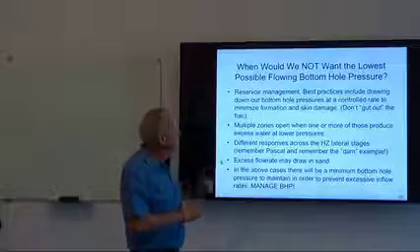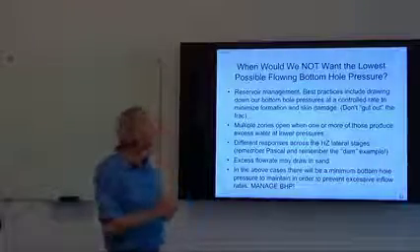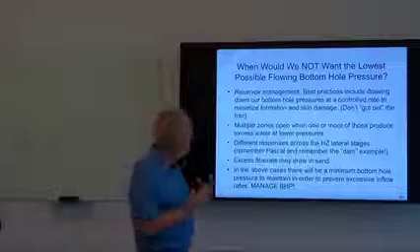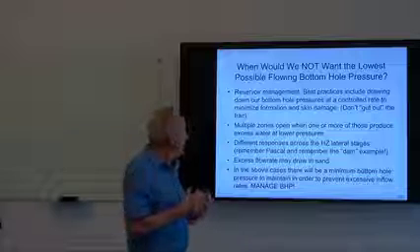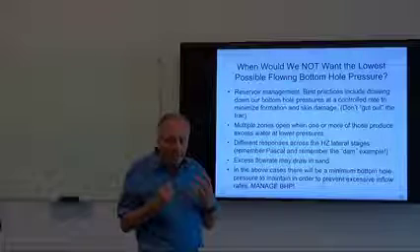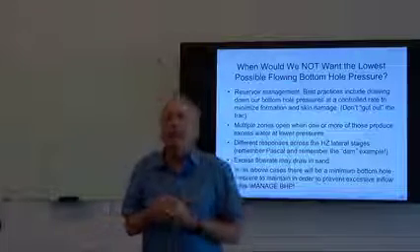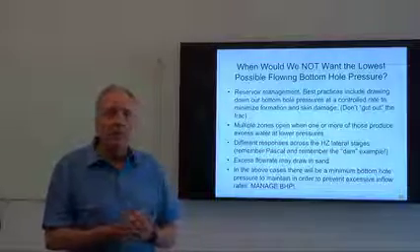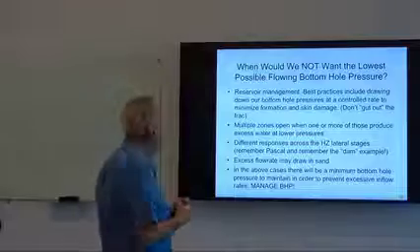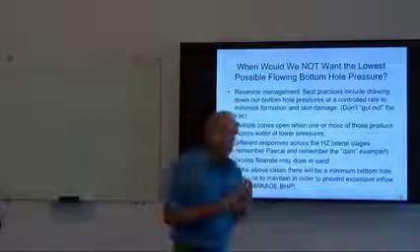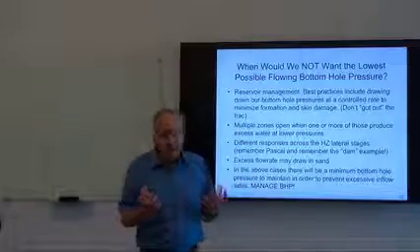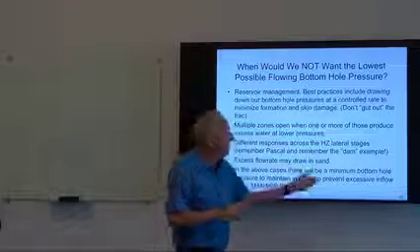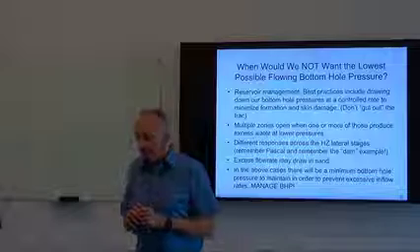As I said earlier, excess flow rate may draw in sand, but in most of these cases it means that there's a minimum bottom hole pressure at any given point in the life of the well that is somewhat ideal for the well at that point in its life. And we want to not only prevent holding back our production, but we also want to be very careful that we don't have excess inflow.